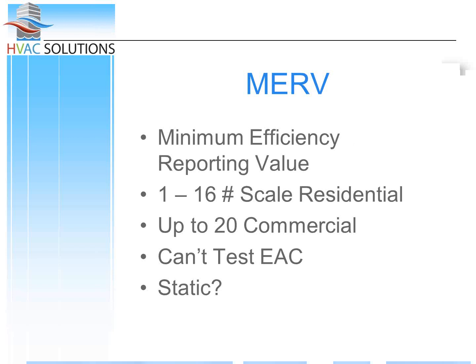And until you get into a MERV 13 filter, what I want you to see is that at less than 1 micron, you're not really catching a whole lot. That's really what I wanted to point out. Beyond that, for things above 1 micron, you're pretty much the same from a 9 to a 13. It doesn't change a whole lot. But the big difference is once you hit a MERV 13, you're starting to catch particles that are sub 1 micron.